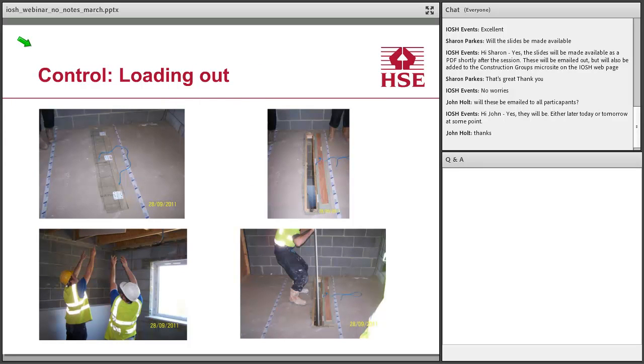One solution is, if you have got wooden floor, is to use what's called a letterbox, where the boards are fed directly through a slot in the floorboard. Yes, it's still manual handling, and yes, there's still quite a lot of weight, but it does stop people having to carry them upstairs and reduces obviously the lift distance. The one thing everybody has to remember is that letterbox floorboard has to be replaced, otherwise you get squeaky floorboards and everybody complains.